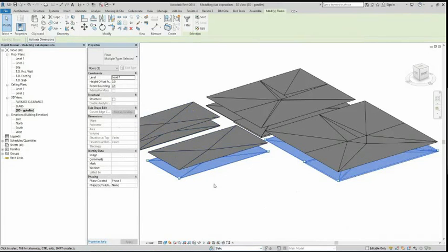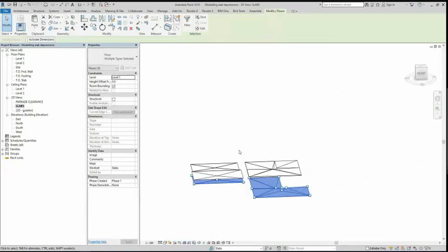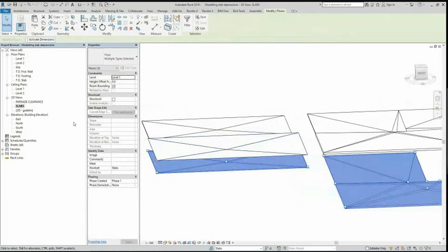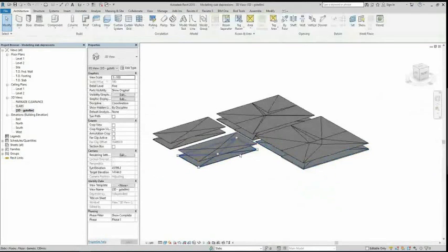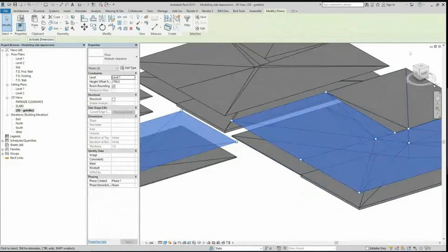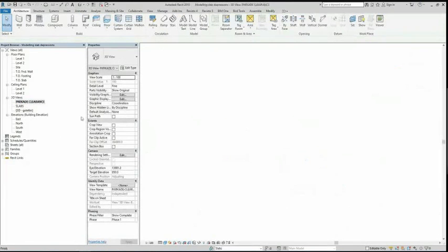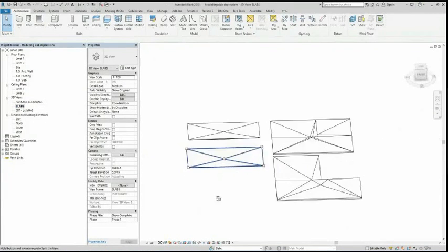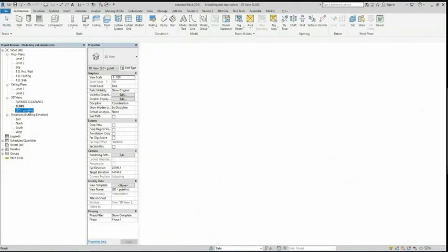Or actually, sorry, I need to do that in this box under parameters. So I'm going to click apply, and I'm going to go to the slabs 3D view, and there they are right there. So I didn't do that for the parkade clearance on the first example, and it's showing up here. So I'm going to go back and complete this process for the parkade clearances now. So I'm going to select all 4 of these and set the work set to parkade clearance. Done. And you can see here that I have all the parkade clearances shown. So again, just to reiterate, the reason why I want to do this, whoops, I'm missing a slab there. Let me go fix that.